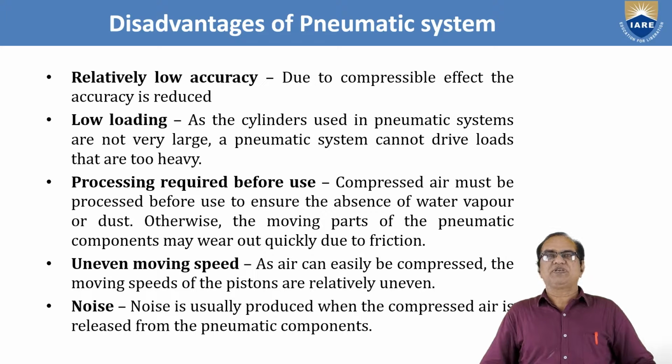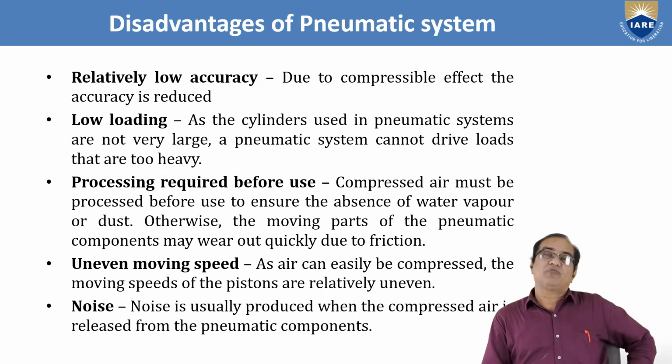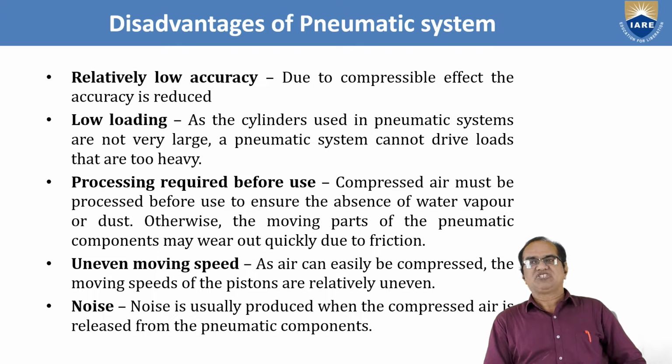Compressed air must be processed before use to ensure the absence of water vapor or dust. Otherwise, the moving parts of the pneumatic components may wear out quickly due to friction. So we need the air to be purified. We need other equipment to make sure that water and other impurities should not be present in the system.